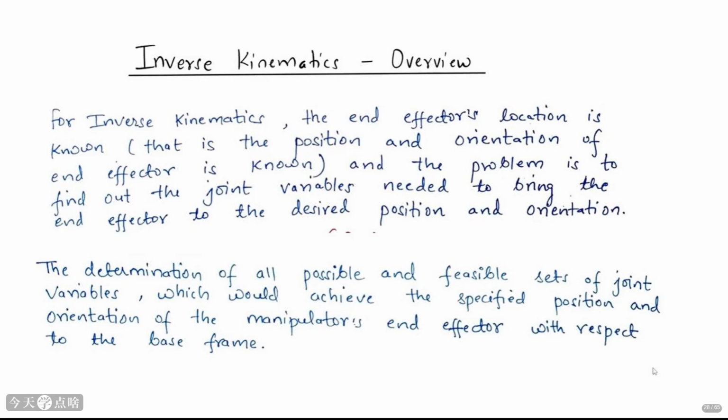So, what is inverse kinematics, really? It's the process of finding the joint variables, the angles and displacements of the robot's joints, that will result in the end effector achieving a specified position and orientation. Given the desired pose of the end effector, represented by the transformation matrix C, we need to solve for the joint variables Qi. This is the reverse of forward kinematics. The handwritten note summarizes this. Given the desired position and orientation of the end effector, find the joint variables. The challenge lies in solving the equations that relate the joint variables to the end effector pose. This is a central problem in robot control and path planning.